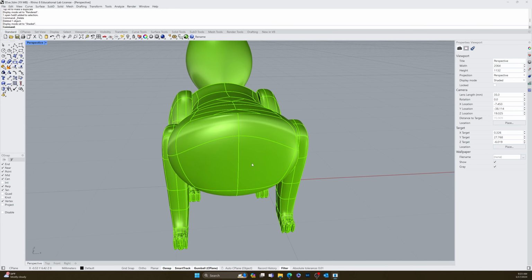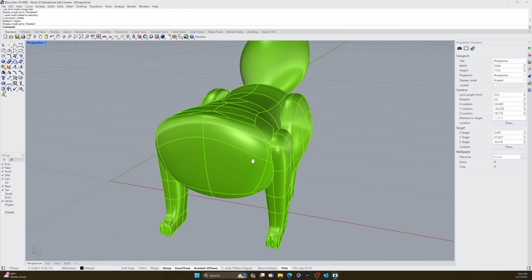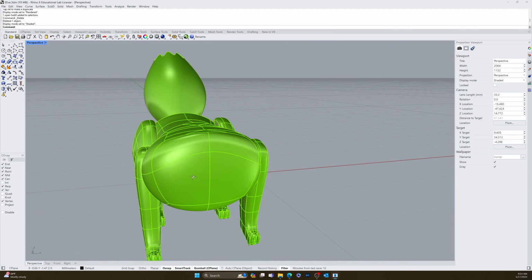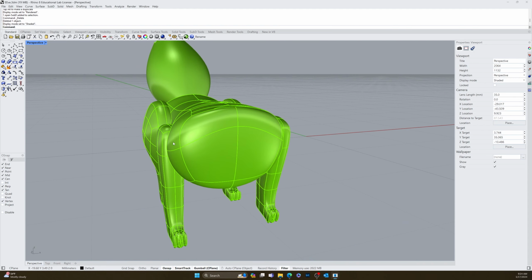And we're going to talk briefly about meshes. A mesh is different from NURBS. Meshes are what is used when we transfer things. Say you design something in Blender, you would export it as an FBX file, which is a type of file that is legible by other software. It's a MotionBuilder kind of format that also includes all the materials and stuff. You can bring that into a game engine, all that kind of stuff. So it's more of a ubiquitous language for the topology of a 3D object. Meshes are very standard in the design world when it comes to 3D design. But we need to change this from a NURB to a mesh and back to a SubD in order to get the topology that we want.